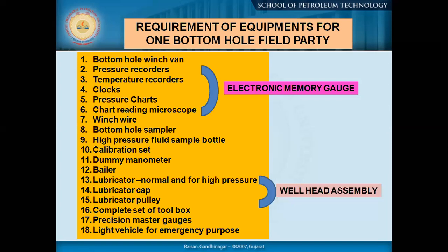Then we perforate the zone of interest. Then we activate it, because sometimes even if you perforate, nothing will come into your well, because you may have some skin which is not allowing the reservoir fluid to communicate into your well. That's why we do the well test generally after casing, perforation and activation. Activation means once the fluid is entering your wellbore, at that time you can do it. Clear? While producing we can also do the well testing.